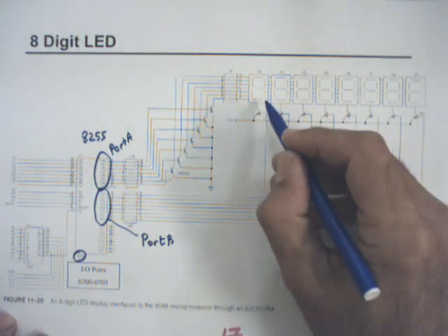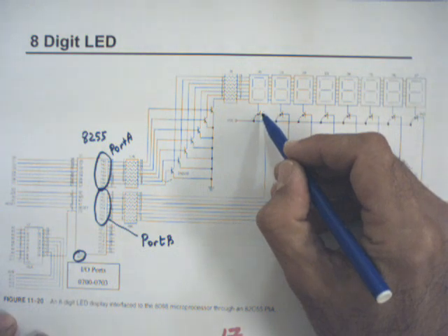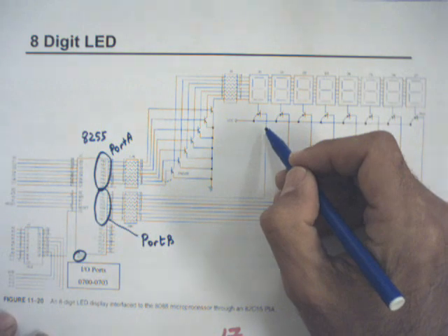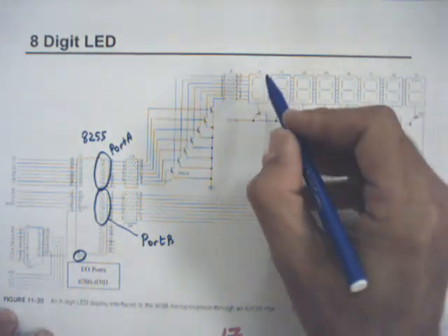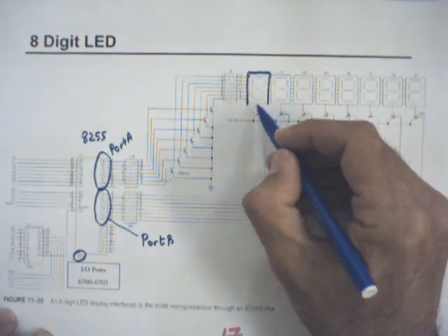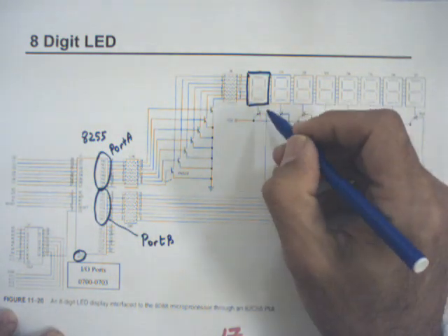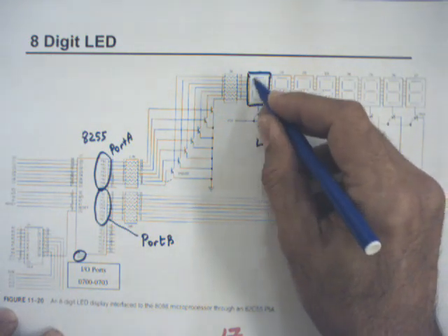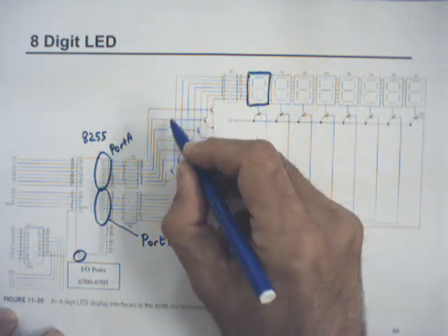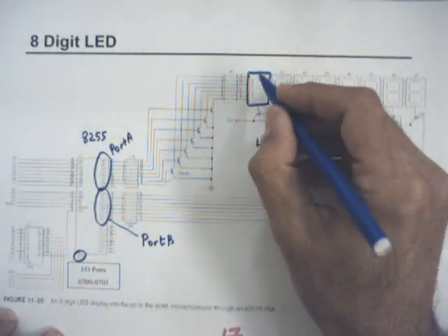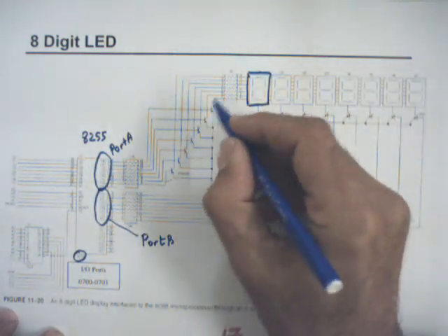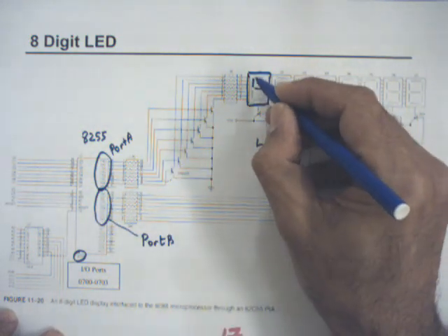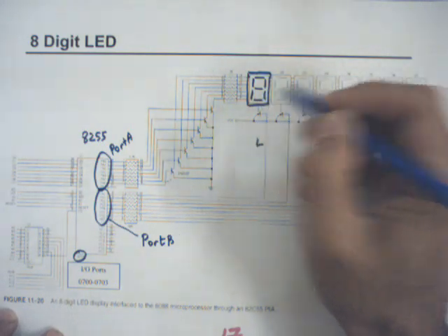So you can blink at least one LED by sending low signal. Once again, if you want to turn on any number at this 7 segment display, you send low signal to PNP, activate the LEDs, you activate certain information. For example, if you activate all transistors, all signals 8, then all segments will be on and you see 8.